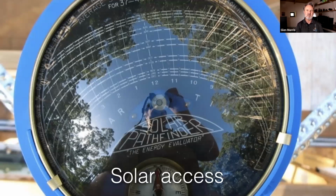It's probably hard to read, but the bottom arc is December and it goes through to the top arc, which is June. If you look carefully, you can see there's a whole lot of trees in the picture as well. The trees are obviously providing some unwanted shade on the solar system for this particular design. So it's a very useful tool for calculating the shading on a site.